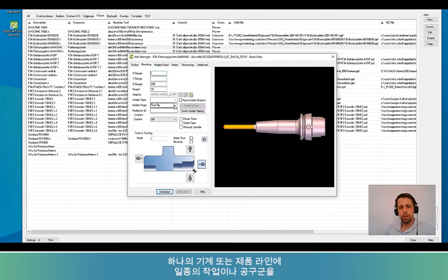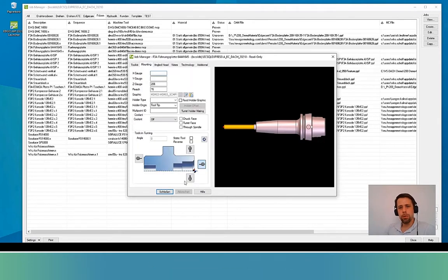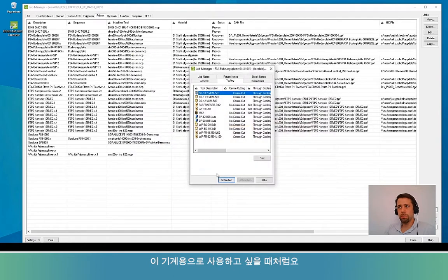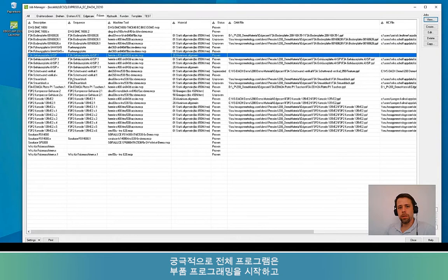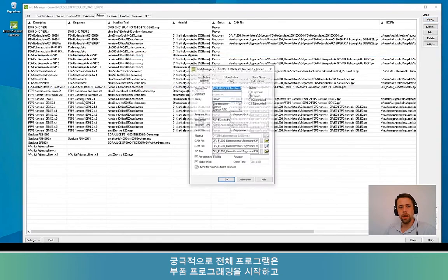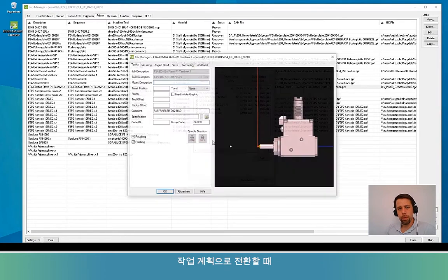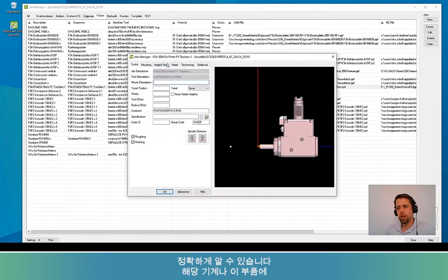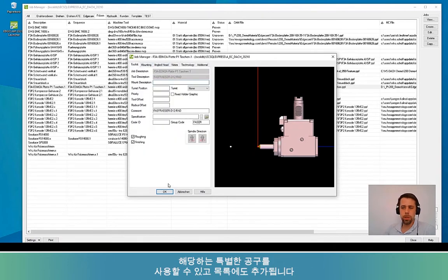You can say you've got some kind of work group or family of tools for one machine or for one product line, where you have some specific tools you only use there, or you want to reserve for this machine. And when the programmers start programming the part and switch to this work plan, they see exactly, okay, I've got these tools on the machine, or for this part we have these special tools, and they have them in their list.